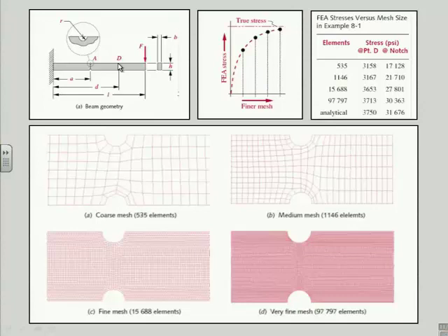One nice thing about FEA is the stress analysis comes out in the wash. It's automatic. It shows me it. I don't have to bother with factors of stress concentration and that stuff, okay? It's going to just show up. But it only will show up accurately if I have a fine enough mesh, particularly around the notches.